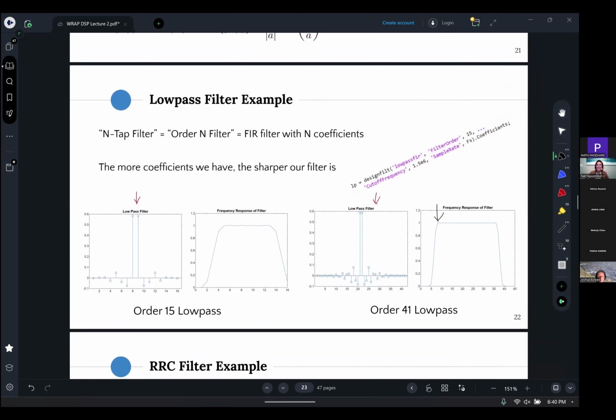Oh yeah, Bart. Are the filter values stored beforehand? Yes. Most of the time they're pre-calculated because it's really easy to just calculate it in MATLAB, for example, or in your software, and then just upload and store the coefficients of the filters as an array in your systems.